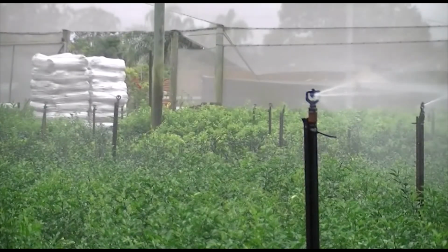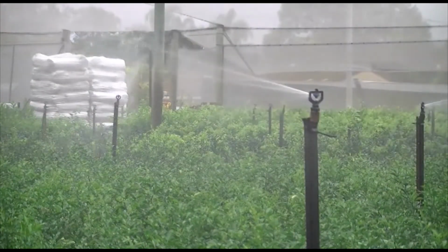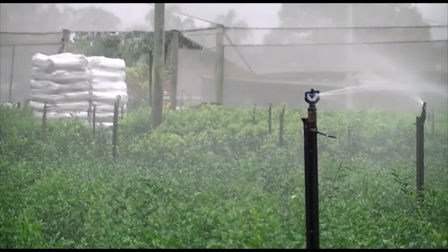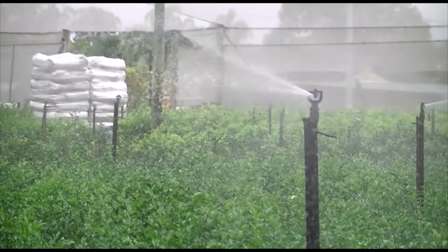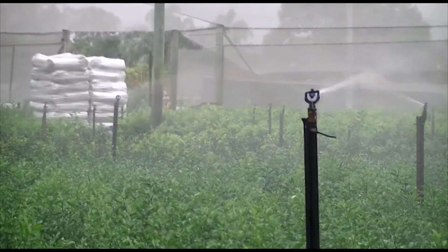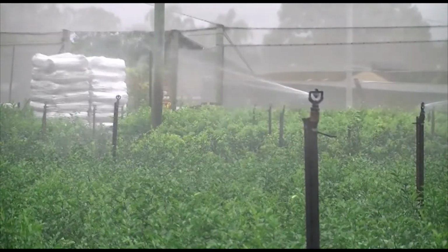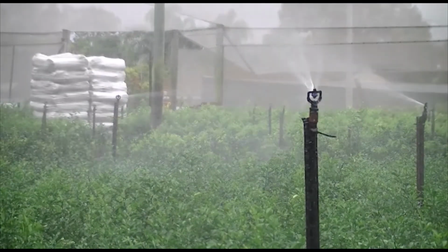To do a catch can assessment of an overhead sprinkler system, it is first necessary to gather some information about the sprinklers used. Sprinklers are designed by their manufacturers to operate within certain pressure ranges, and the distribution pattern of a sprinkler can be altered dramatically with a change in operating pressure.